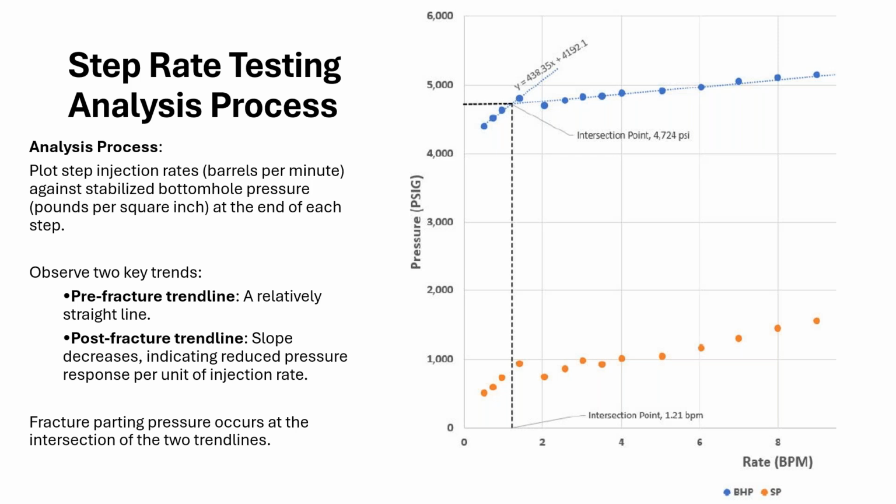If you don't see a step rate or a breakover during that test, you can say that the well will operate below fracture parting pressure at the rates requested. And if the regulator does not feel that is a sufficient test, you can use supplemental data to confirm your case.